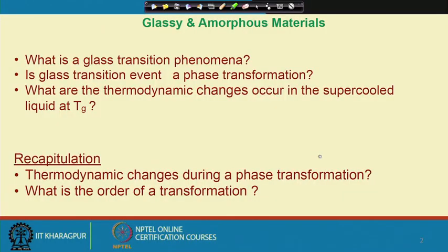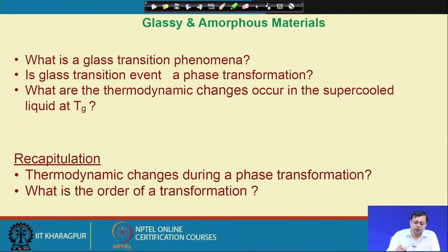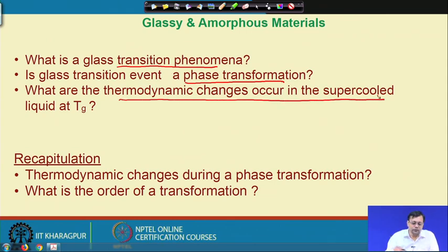So, the basic question that always rises in our mind is what one should understand, and what we really mean by glass transition phenomena. And whether this glass transition we are talking about is really a phase transformation or something else. On the other hand, what are the thermodynamic changes that occur in the supercooled liquid at Tg, because we already understood that glass transition is manifested during cooling of a supercooled liquid.